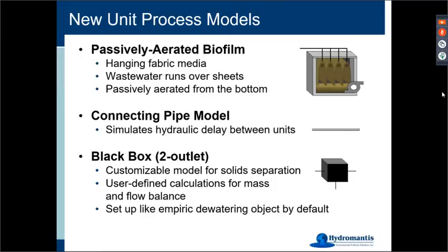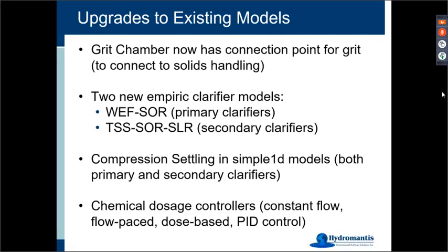So just a few words on upgrades and changes to some of the existing models. That was all the new models that I just showed you. We made a change to the grit chamber. So now the grit that's being removed can actually be connected to and taken to another part of the plant so that you can keep track of those solids.